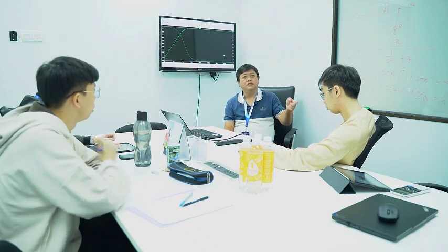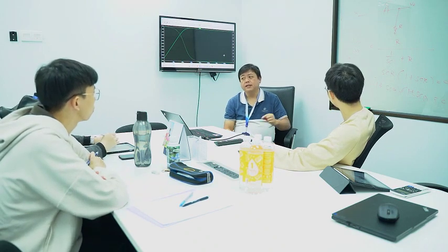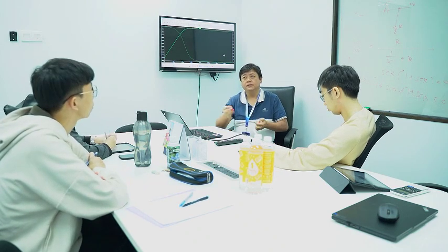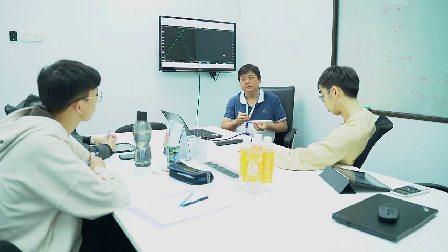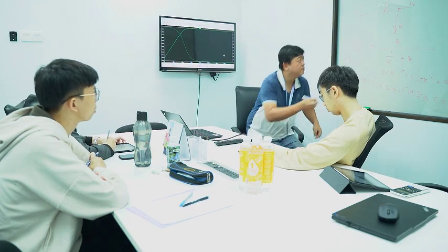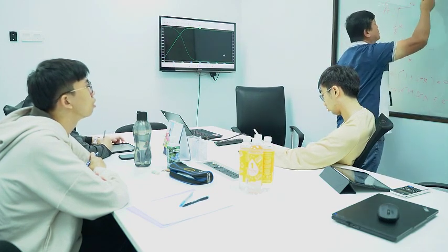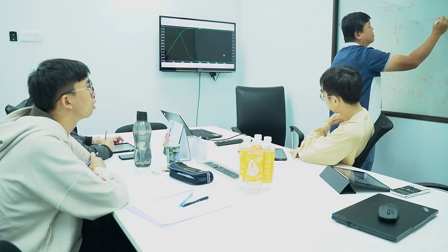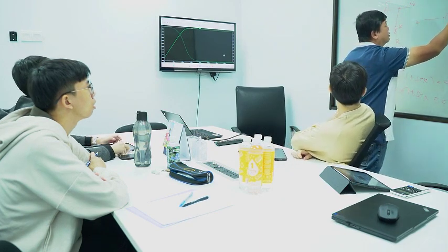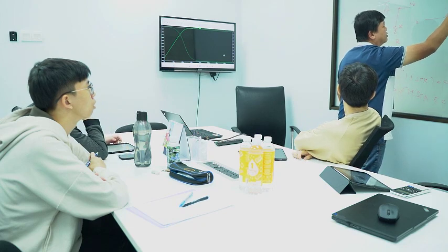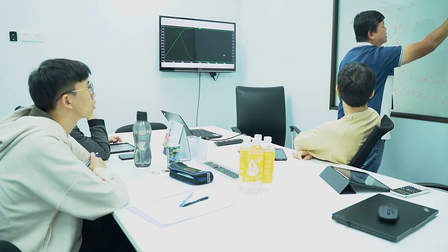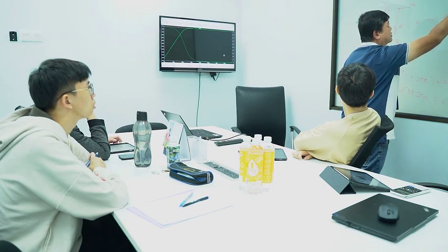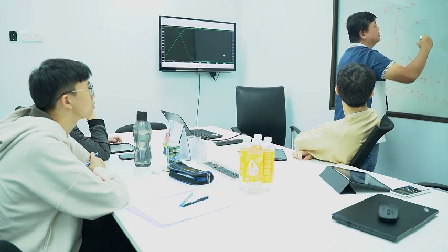That's why the PLL can be stable, because it has minus 180. After that, there's a 0 coming in. Now, if you look at the curve of the PLL phase shift, you still remember, you start from something like this, minus 180, right? After that, there's a pole, there's a 0 there. So it makes the system stable. Let's say this is the UGF. So it makes the system stable.